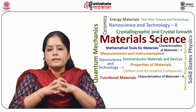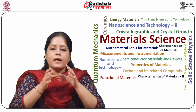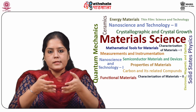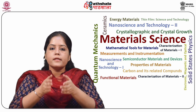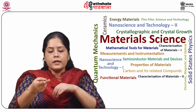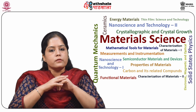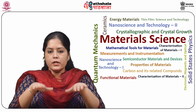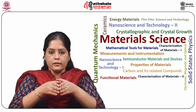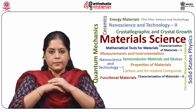So students, let us now discuss the fabrication of CCDs. CCDs are fabricated on silicon wafers and are processed in a series of complex photolithographic steps involving etching, ion implantation, thin film deposition, metallization and passivation for various functions within the device. The silicon substrate is electrically doped to form p-type silicon.